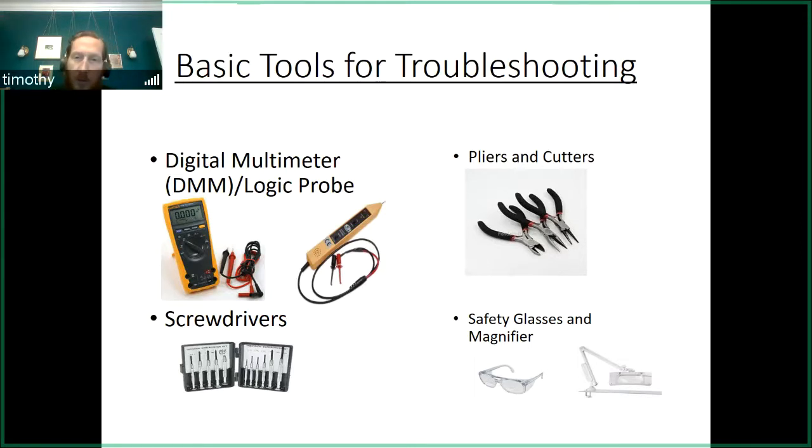You're going to need pliers and cutters for stripping wires, putting components in, screwdrivers for putting in the standoffs, screwing in wires into terminal blocks, safety glasses, magnifier. These circuits are very small, so use the magnifying glasses. Use the safety glasses. If you are debugging something and you accidentally short it out and it's a hot circuit, it can blow up, and you want to protect your eyes.